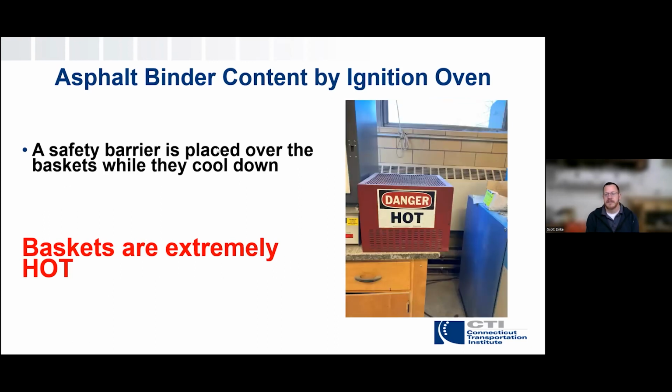And so another element with that is we have these barriers. Okay, the danger, hot, yeah, absolutely. If somebody were to walk by in your laboratory or in our laboratory or whatever and just brush an elbow on those hot baskets, they're going to get burned very, very badly. That's an extremely hot temperature. That's not your standard oven temperature. You know, if you're baking a potato or something like that, it's quite a bit hotter than that. And so we need to again exercise plenty of safety measures, using again gloves, face shield, tongs to handle the baskets, and then barriers to protect people from touching those baskets as they're cooling down once they've been removed from the ignition oven.